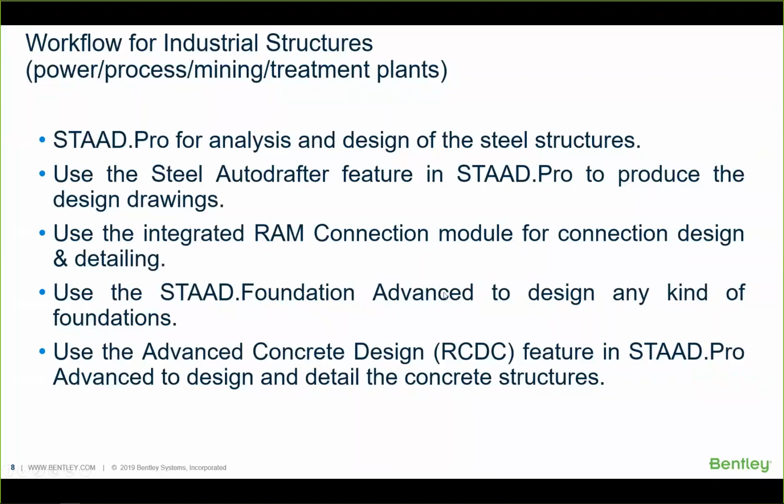And foundations can be designed using STAAD Foundation Advanced, which can also be launched directly from STAAD.Pro to read the support reactions from the superstructure and proceed with design and detailing of foundations. Any type of foundations, like isolated footing, combined footing, pile cap, or mat foundation.